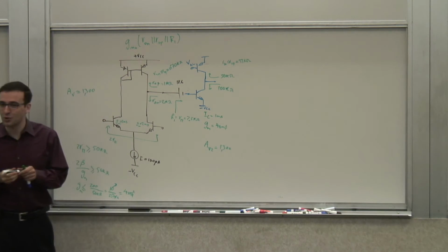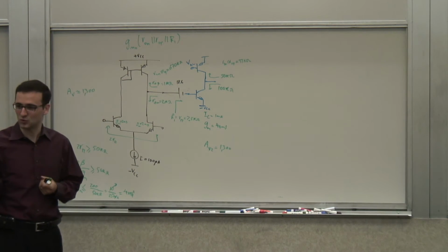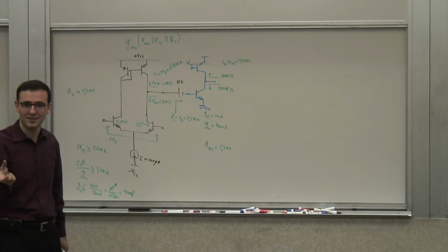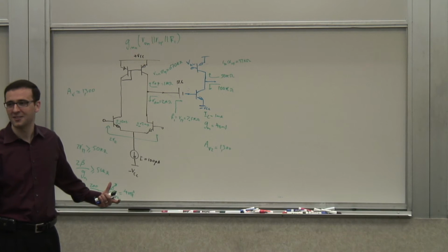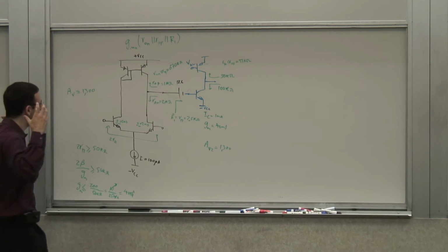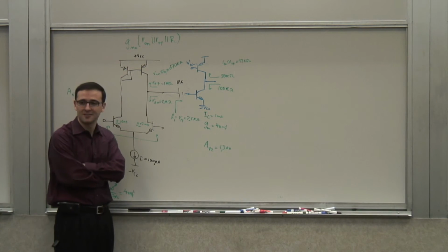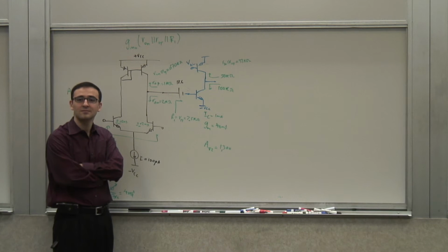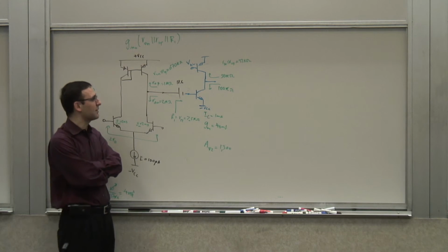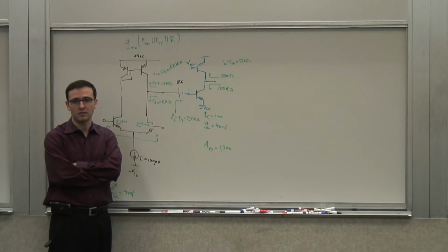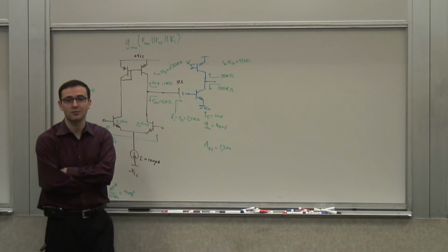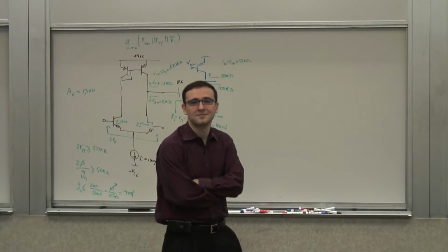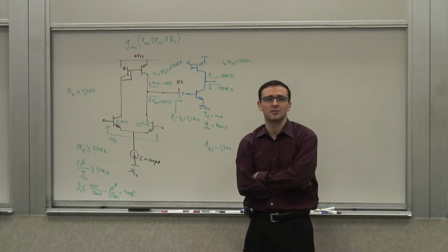18.6. So you don't have that problem with the drop, right? With the gain loss. Because from an AC perspective, it's a short. Right? If you could even use a battery, would this work? Or capacitor. Well, or capacitor, but the capacitor always has a low cutoff frequency, right? It can't pass DC. So then you have to think about that. The good thing about a battery is that it is a capacitor which works down to DC, and has a fixed initial condition.